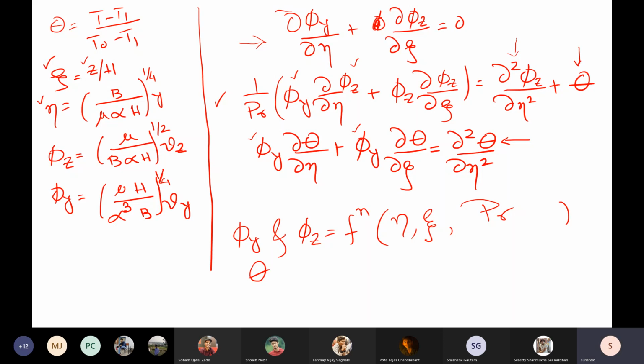And we understand that because the left-hand side of this equation, these two, refer to convection. And in free convection, the flow is rather slow. So the effect of the entire left-hand side, be it momentum transfer or energy transfer, will be rather small. Everything is going to be governed by the viscous forces and buoyant forces, which are essentially the first term on the right-hand side and the second term on the right-hand side, respectively.